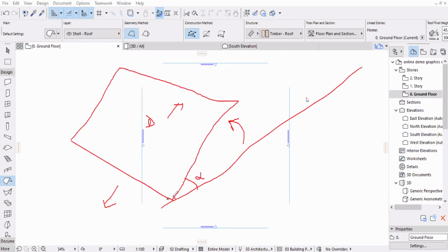So first it will ask you to define the pivot line. We have to define it by defining 2 points. When we define 2 points, we get a line. And then the second option would be to define the eye cursor, which side you want it. And the third option would be to draw these edges. You'll have to draw the complete edges from point to point. Is this clear? So let's do it.